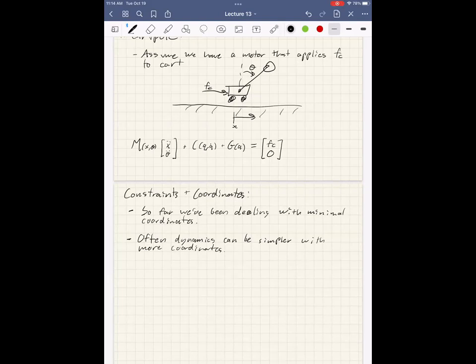And instead we want to use something like quaternions, where you've got an extra coordinate, but now things are kind of quasi-linear and well-behaved and they're not singular and all that kind of stuff. But now we remember when we did the quaternion stuff, you pick up a new constraint, right? So now that's 4-dimensional, better behaved, but you also have this unit norm constraint on the quaternion, right? So that's an example of this we've already seen.